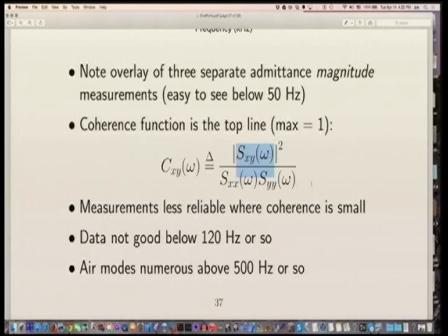So the Fourier transform of that would be the frequency response of the system, and then we're doing a magnitude squared of that. And then let's say our input was an impulse, that goes away. And what's Syy? Well, it's going to be the magnitude squared frequency response. So we expect 1. So the coherence function for a linear system should always be 1. Now, why might it not be 1? It might not be 1 if we don't excite all frequencies.